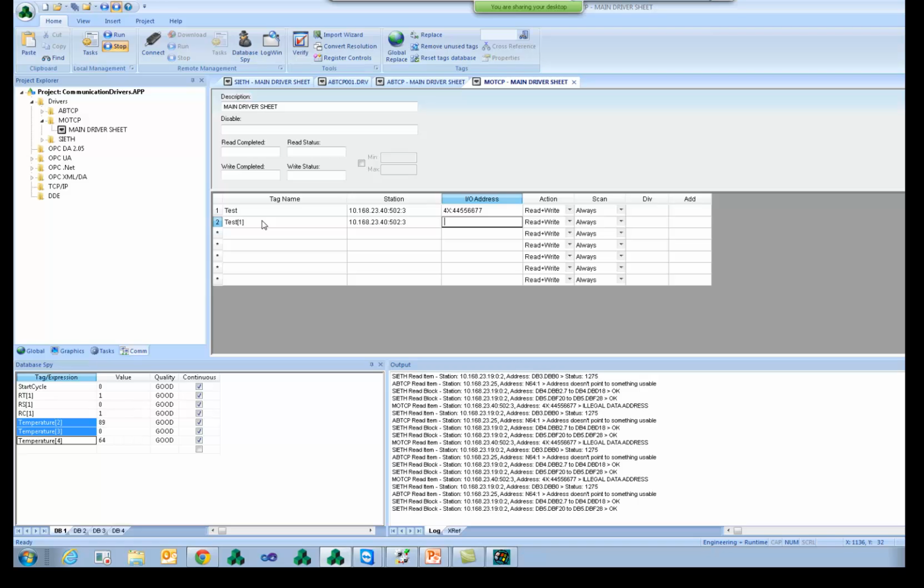So on Modbus, for instance, on the PLC, this is my address. Some other PLCs you may have only 5 digits, other PLCs I have 6 digits for the address. So for us, we're gonna consider that you put the number that defines what that address type is. You know, 3 for like 3000s for input reads, 4000s for read and write words, 0x for read and write bits, 1x for read-only bits. So here we have one address. I'm talking to this guy.